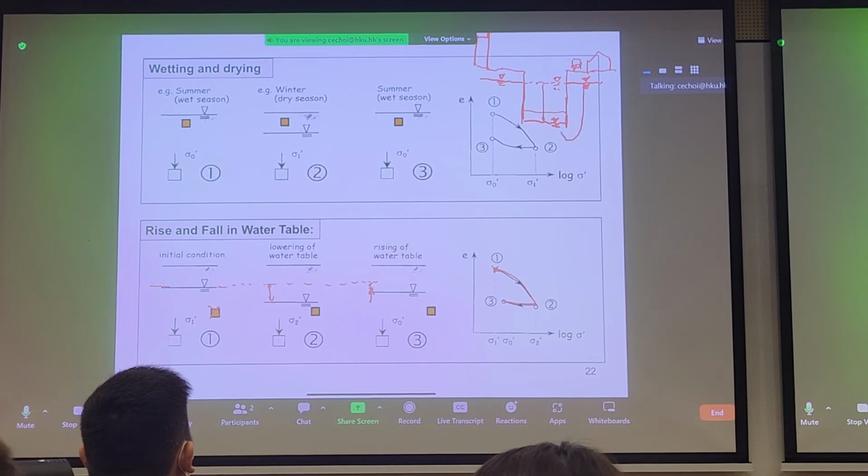When you draw this down, what's going to happen? Well, you're going to form seepage, right? The water's going to go this way, and then this water table is going to come down as well. When this water table comes down, we might see consolidation outside, right? If it hasn't happened substantially. What happens when you consolidate soil outside a cofferdam? Well, you might see this infrastructure wanting to settle. So we have to account for these things when we do a sensitive impact assessment for our construction site, when we draw down the water table.